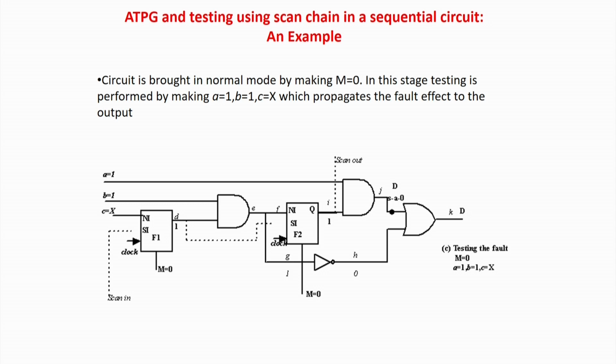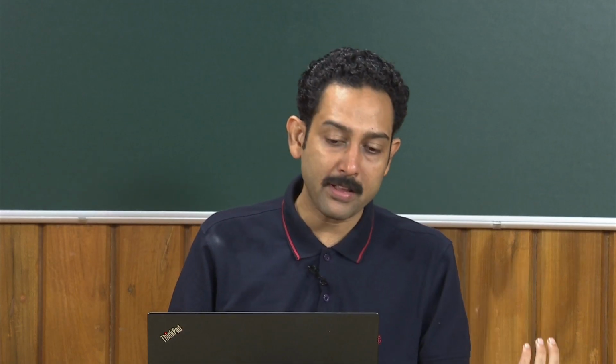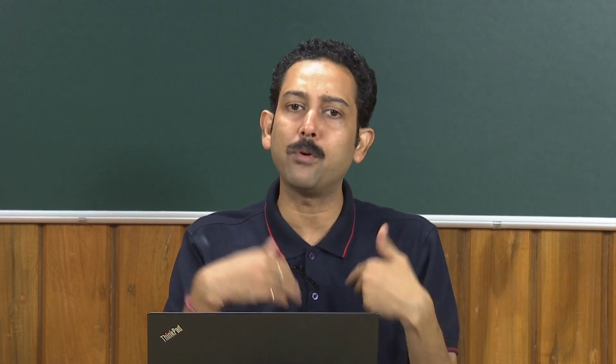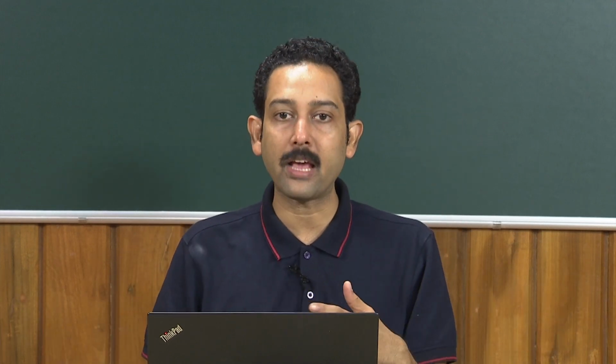Can I partition the scan chain? This is a partial scan: can I put some of the flops in scan mode and leave some as they are, so that at least some area is saved, and at the same time I have less time to push in the test patterns, because now instead of one chain I will have many parallel chains. But many parallel chains mean many pinouts at the same time. So I cannot have 100 parallel scan chains. So how will I make a trade off?